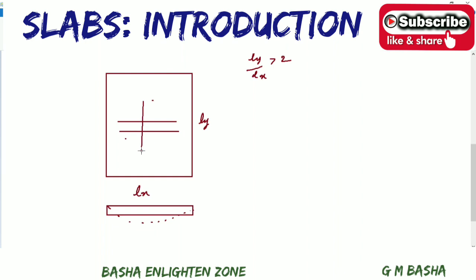We will discuss that along with one example also. Just to remember the concept: one way slab bends in shorter span direction, therefore we require main reinforcement in the shorter span direction. I will mention those indications also. These two are the main reinforcement, that is main steel, and these two are the distribution reinforcement.